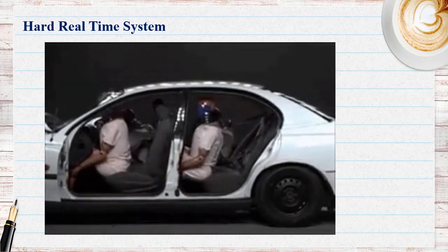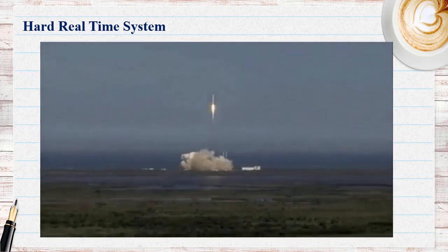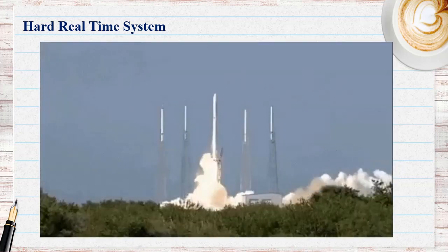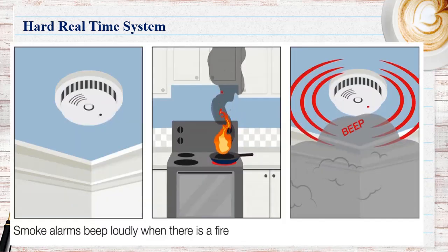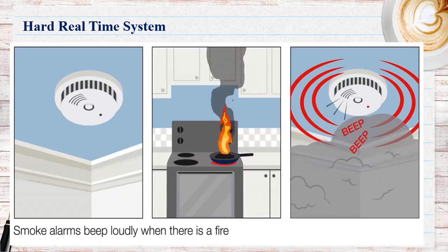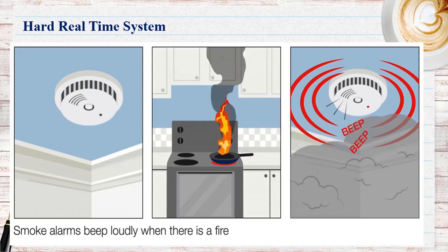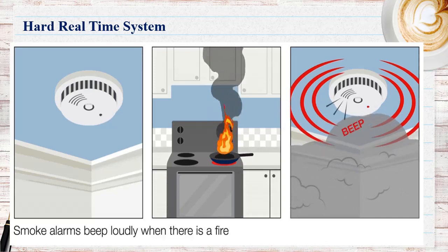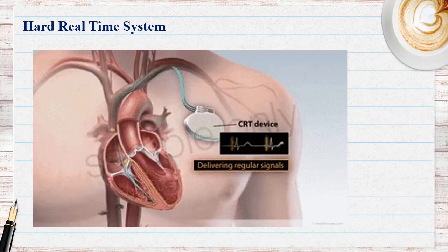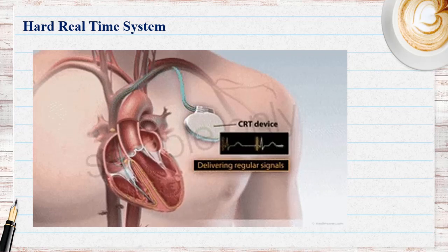The hardware and software of hard real-time systems must allow a worst-case execution analysis that guarantees the execution be completed within a strict deadline. The chip selection and RTOS selection become important factors for hard real-time system design. Example: deadline in a missile control embedded system, delayed alarm during a gas leakage, car airbag control system, a delayed response in pacemakers, failure in radar functioning, etc.